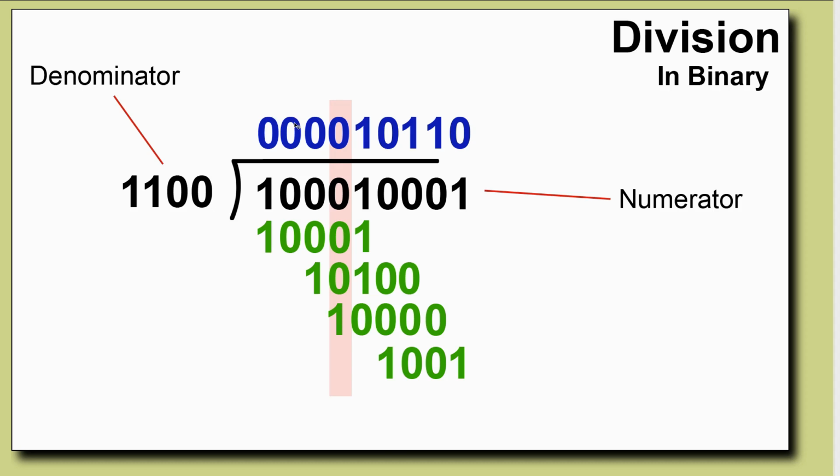So if we code up an 8-bit divided by an 8-bit, and then we do that twice, but with the second time, instead of starting the remainder at 0, we start it at whatever the remainder from the previous operation is, we will get the low and the high bytes of the result from those sequential operations. This is a really good property for us. Whatever it takes us to do an 8-bit by 8-bit division, we can double that to do a 16 by 8 and double it again to do a 32-bit by 8-bit division. That's nice linear performance scaling, which is a property we like to see in programming.